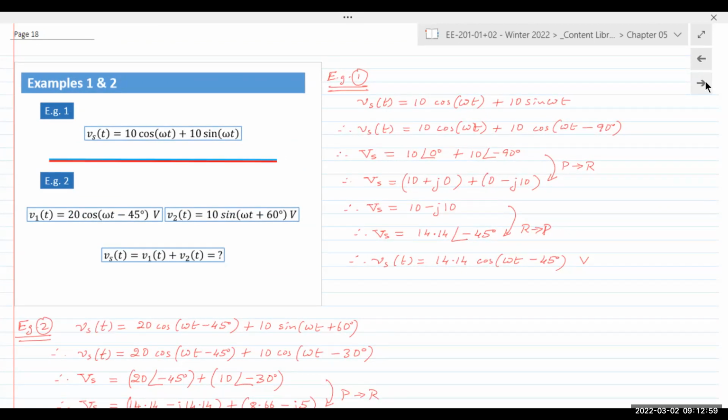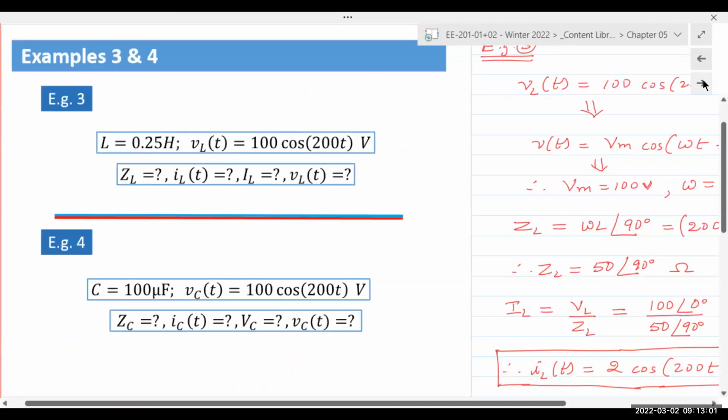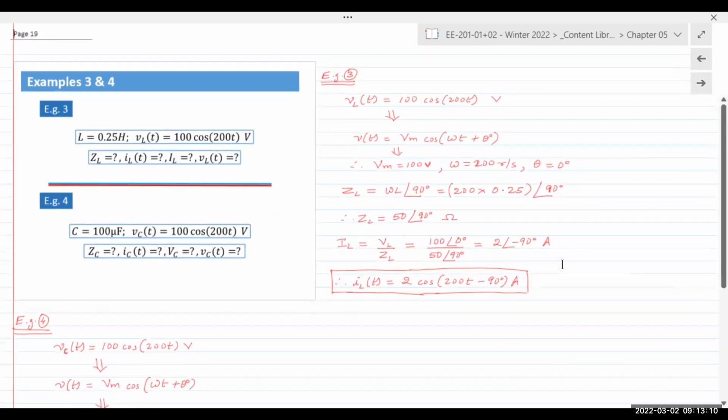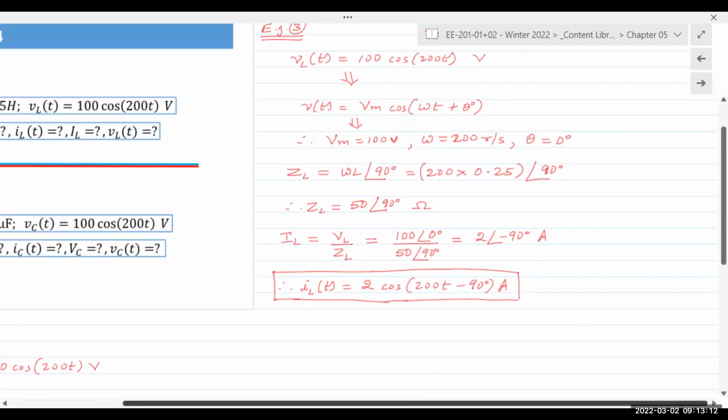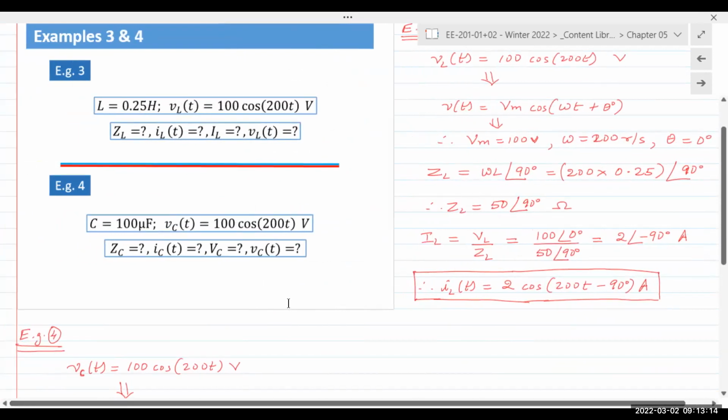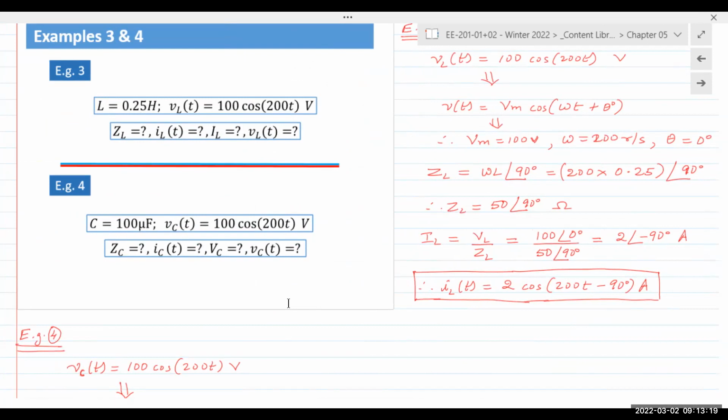And we do the same thing with components, specifically inductors and capacitors, which have reactance. That reactance is represented by the complex number J in electrical engineering. And then we can apply all the analysis techniques that we have learned in chapters 1 and 2 to solve for AC currents and voltages.